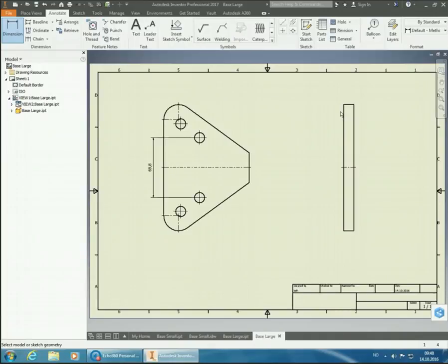Now this is a typical example of where, most likely, what I would guess in a situation like this is that this base plate is going to be bolted to another structure, and for some reason that structure has these weird dimensions between the bolt holes. It might be that the original dimension has been set in inches. Then you usually end up getting point something in millimeters. So that might be as easy of an explanation as any.